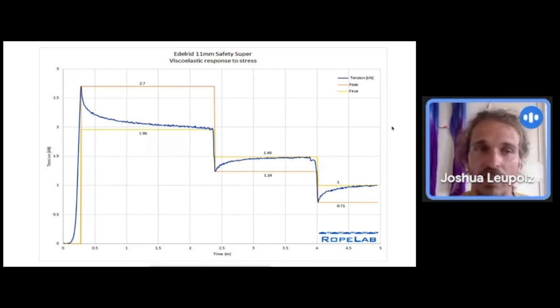tensioning and detensioning. And this is also linked to the dampening effect. That's exactly where you lose energy basically. So you tension it up and you lose some stretch, which when you release, you don't get this energy back anymore. So there is some dampening happening, and the slower you stretch something out, the more losses you have over time.